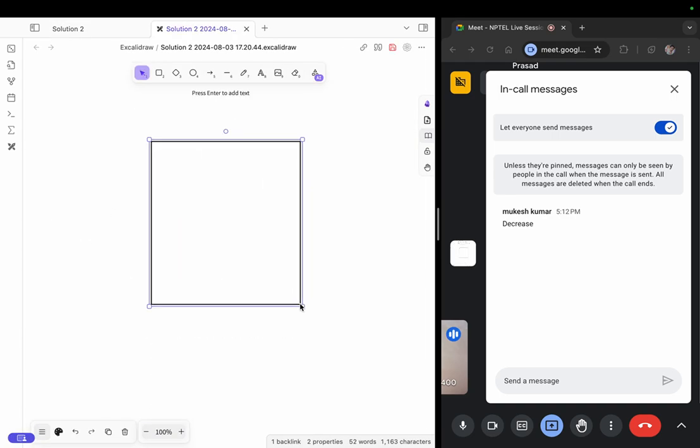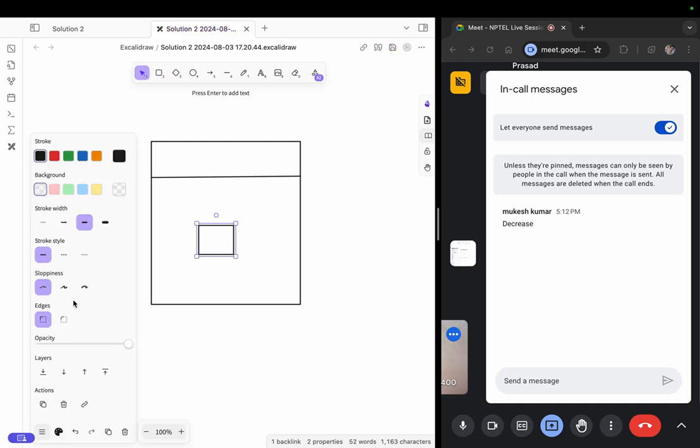So if you have some container like this and then you have a liquid inside the container, let's say this is the level up to which liquid is filled, then if you consider a control volume or a small block inside this, on this fluid element there will be forces from all the directions that will be balanced. That fluid element is at rest, which means the net force on that should be balanced from the top and bottom. If you apply that balance, the pressure that this particular fluid element will be experiencing is what we are calling hydrostatic pressure.